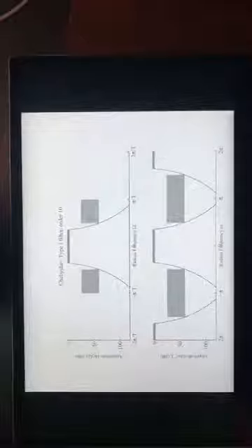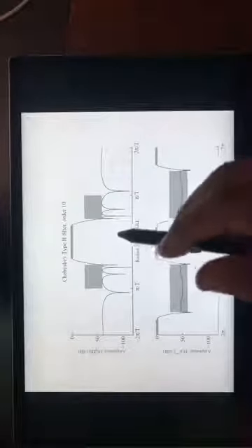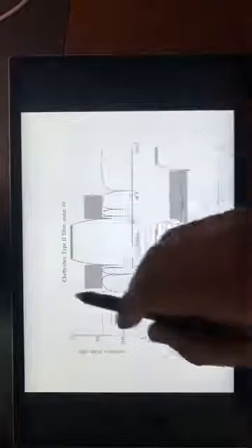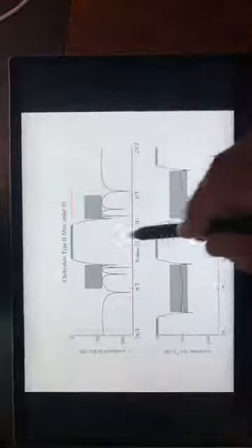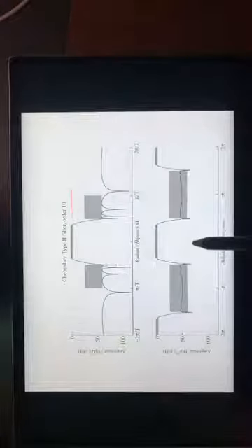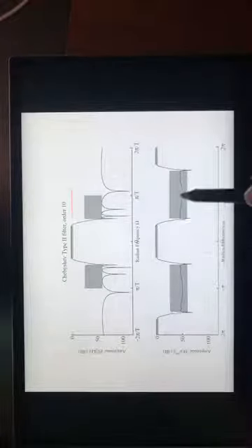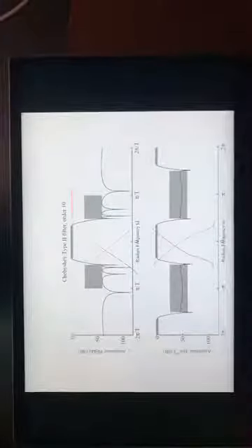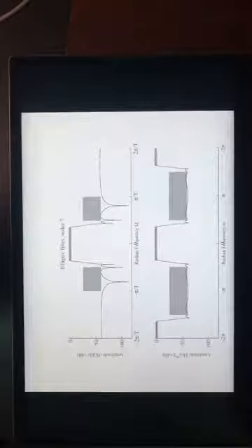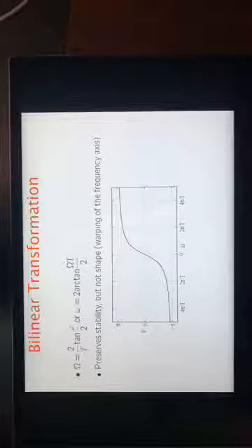So you are designing, this is a good example, a filter using the Chebyshev type 2 technique, order 10. But once you convert this into a digital filter, it no longer meets specification. So you say, whoa, I don't want this because it is not meeting my specification. So I need some other technique. So this is not meeting specifications, and that is the reason we came up with this.